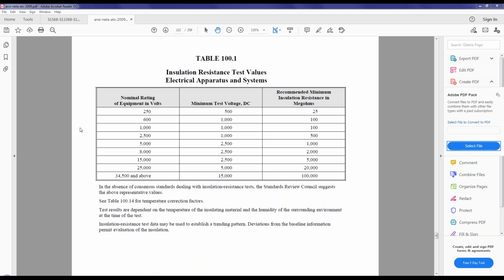What is the best thing to do if, while conducting an insulation test, you see the reading jumping or not stable? So that could be because you have a high capacitance in there, sir, where the capacitance is being charged and then discharged again. That's why you have a very unstable reading. So I would suggest you do a time-based test, the DAR and polarization index test, for those kinds of situations.